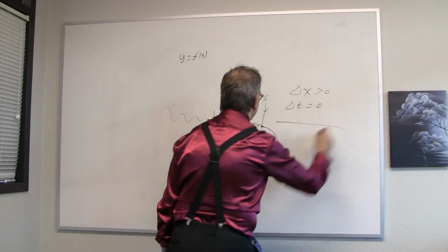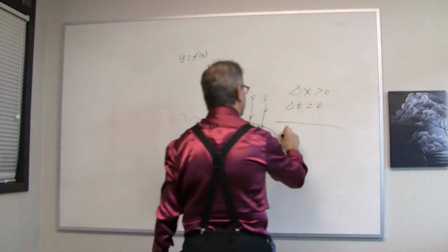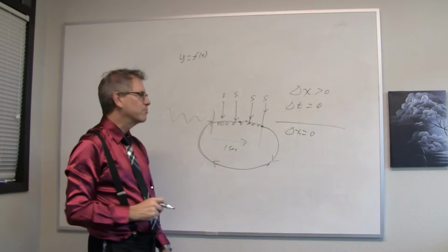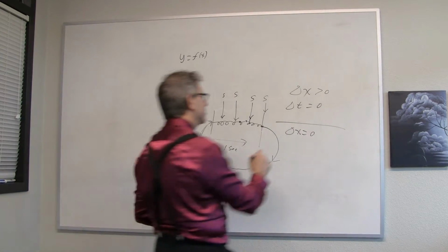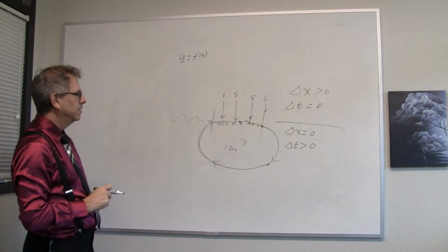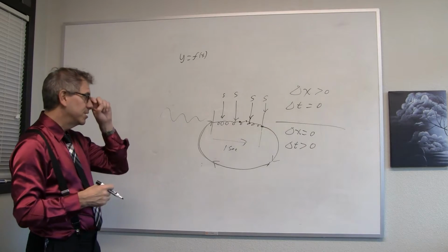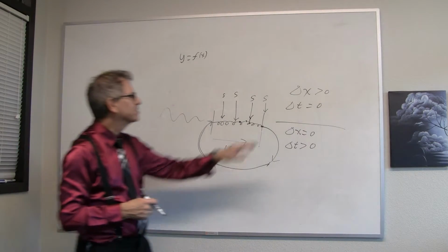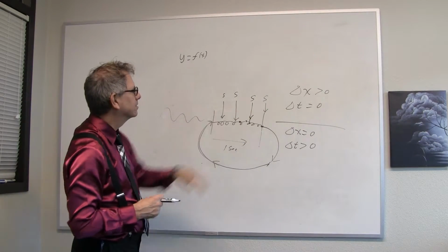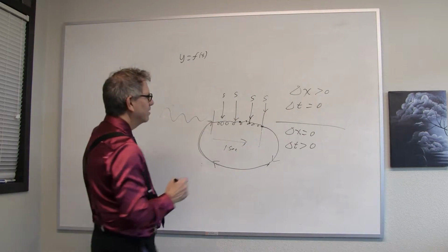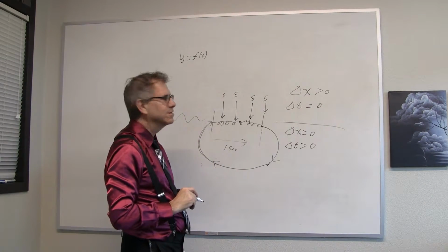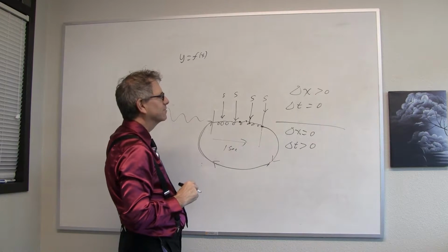The other extreme, where we only had a single sensor, there was no error in the position we were reading because we waited until that position was exactly at the sensor, but we had a time penalty. And we can find spaces in between here. For example, if we're willing to accept a small time penalty, we can have 4 sensors in here, and we can wait for this to come all the way over to where it can be sensed, and that's a penalty of 1/4 of a second.